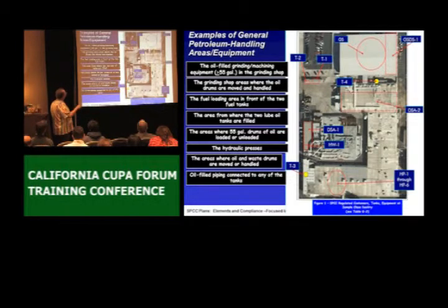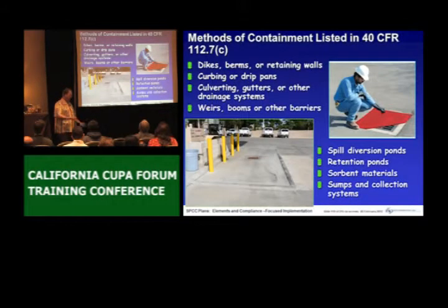These are all general containment areas: the loading area by the tanks, wherever you're driving in the drums, and your oil-filled equipment areas. Very typically, what do facilities use for general containment? Active measures, spill kits, active response. Make sure it's credible. Don't just say, yeah, we'll respond to a spill. We have spill kits and one drum of half-filled sorbent.